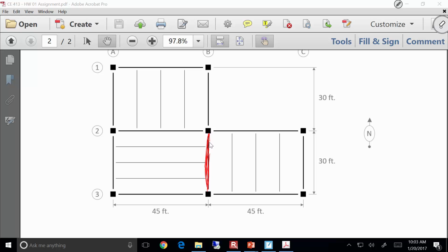No. And why? Because you only have beams framing in on one side. Yeah, there's only a beam framing in, right here. So for this floor beam, I'm just making up values. Let's say the reaction over here is 4 kips and the reaction over here is 4 kips. Then when you do this girder, it's literally just going to be 4 kips. 4 kips, something like that. All right? If there were a floor beam framing in over here, then it'd be 8 kips, assuming all the dimensions matched. Sound good? Everybody okay? All right.